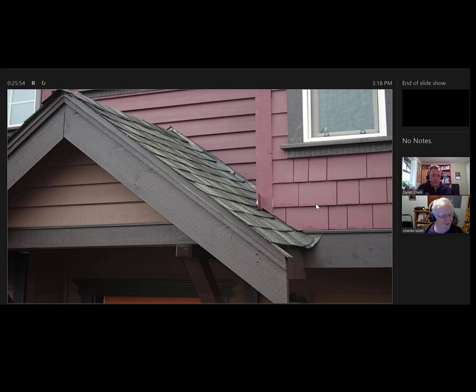See, there's another inconsistency for me in the codes: any flashing, any valley material, any pipe flashing should be rated for the same life as the shingles they're installed with. But we don't do commensurate service life, right? No, we really see that with the heavy roofs, and then they put the cheapo neoprene 15-year plumbing pipe boots. Where else do you see it?